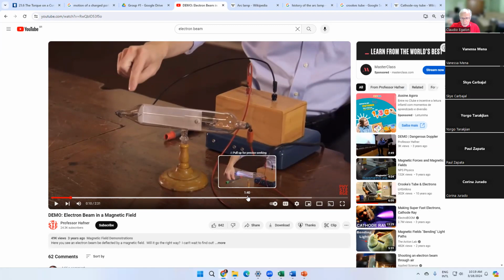If you see a bluish glow, that's because you have some molecules inside that glow as the electrons are emitted from this end to the other one, okay? Take a look how it is. Remember that that's the black terminal of the power supply, which is the negative one, and that's the red terminal of the power supply. That's the positive end. And don't forget, this box here is a high voltage box.